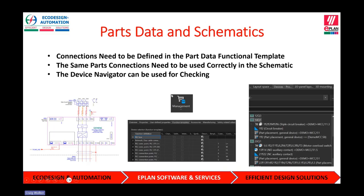So if you go under your parts management and you open up a part, under the functional templates for that part, you have a list of the functional points. This is a PLC box. You can see these PLC points are defined. It's actually for a VSD. A lot of people use PLCs to define VSDs, but it has a connection point designation and a connection point description.